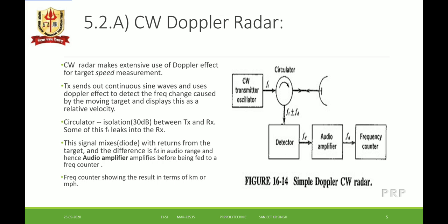The circulator keeps the continuous signal coupled to the transmitting antenna, and the received echo signal, with the frequency change depending upon the distance it has traveled to the target, is obtained by the receiver set.